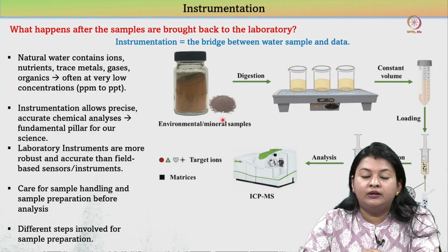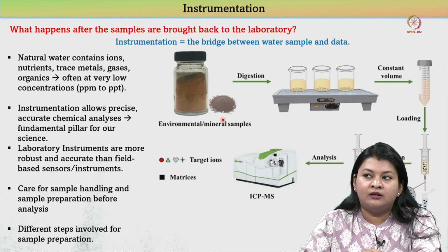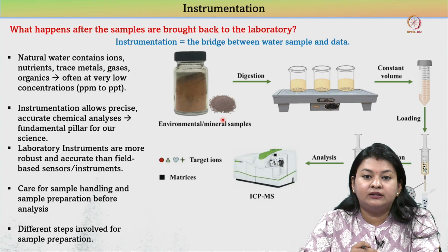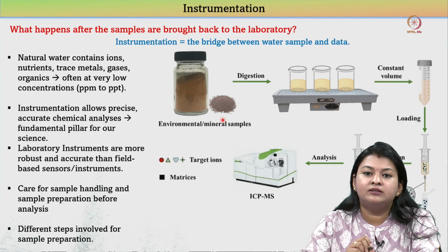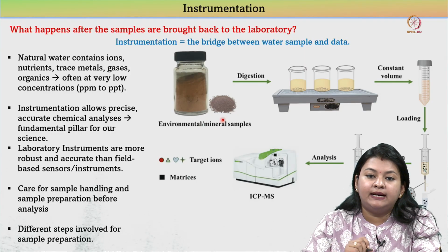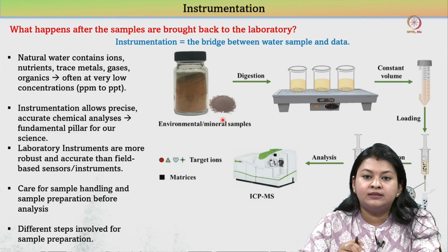Depending on if you are doing acid digestion, that is the most preferred one, because if a lot of organics are there, if a lot of heavy minerals are there that are difficult to digest, a lot of time can be consumed. So, we generally add acids to make it digested. So, always we do acid digestion of sediments. Okay. So, to get the entire sediment into soluble form, we are going to do this digestion.